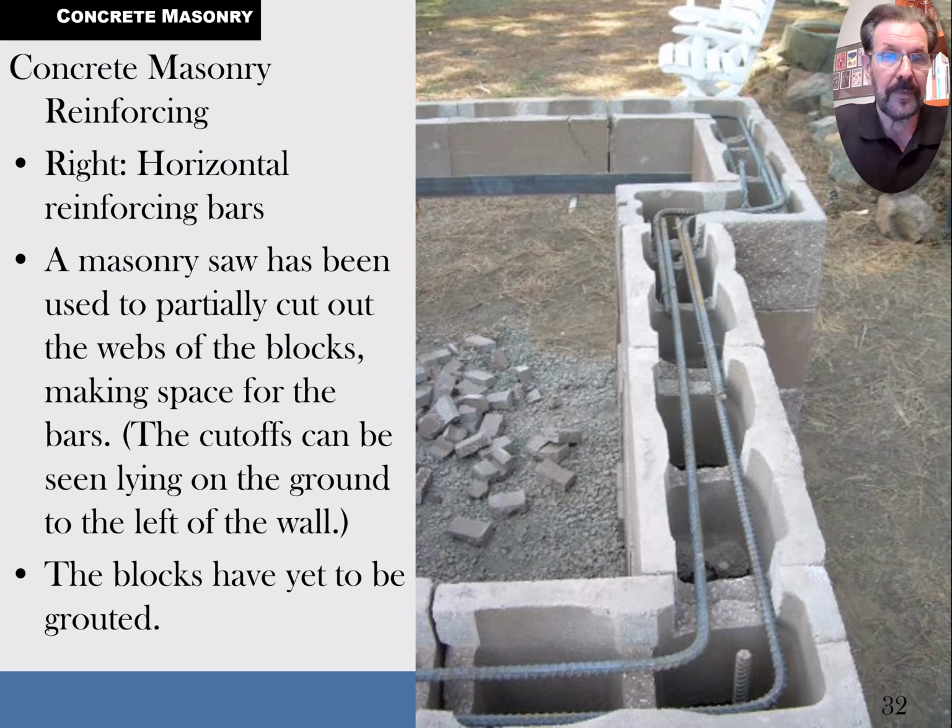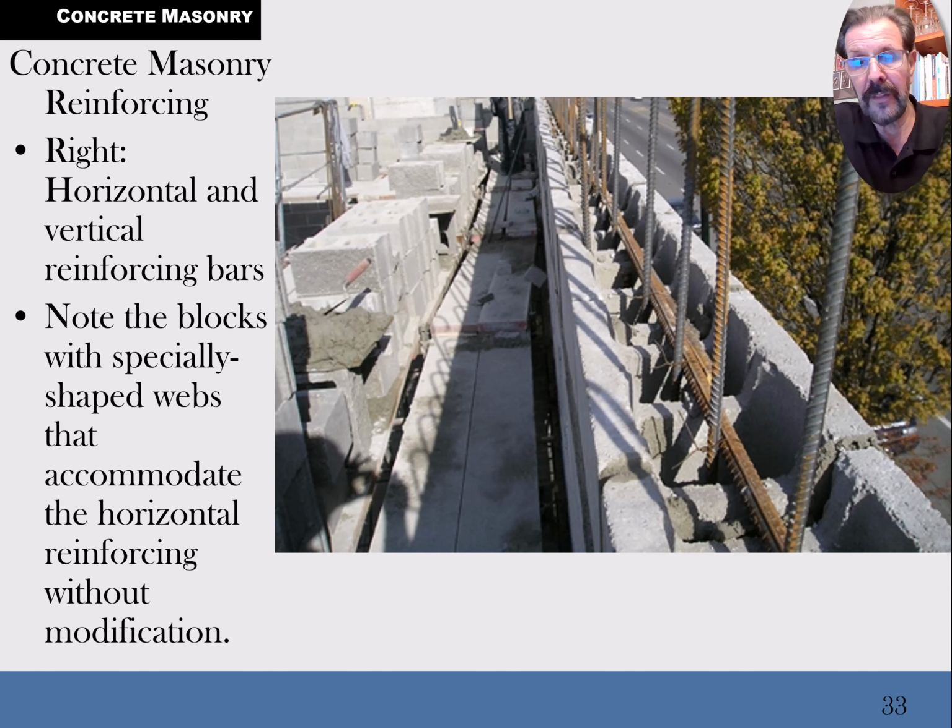Here's another version, a variation on a theme, but this is more about, they've cut this block so that they can deal with pouring a concrete slab that'll be cast in place, but sit right on top of here, or maybe fill the concrete in here in order to actually have a ledge for precast concrete parts to be sitting on that ledge. So they cut it a little different. Here's an example of a bond beam that's precast concrete that's being tied to a wall in the foreground and also one in the background that we don't see. And so that picture is showing another way that you can connect from your bond beam across and still span over an opening of some kind.